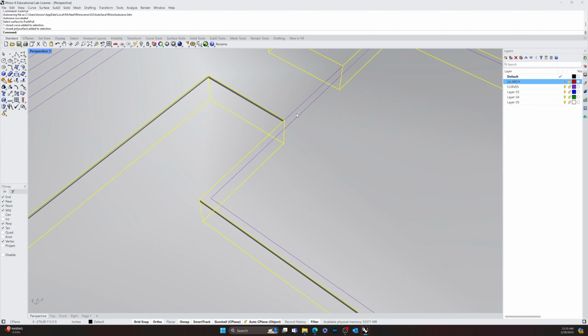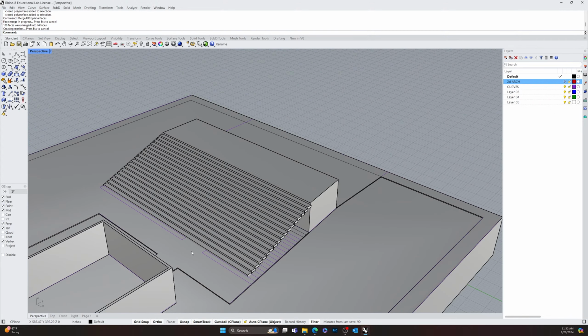And because I've done the math, I know that this bottom extrusion is right at that floor level, and I can just delete that one. And then I've got basically 20 steps here. And I pulled down that bottom so that there's a bit of overlap on each one of them. So I can Boolean union this whole thing into a single piece. And then we can Boolean union them all together like I just said. And merge all coplanar faces just to kind of clean that up a little bit more. All right.